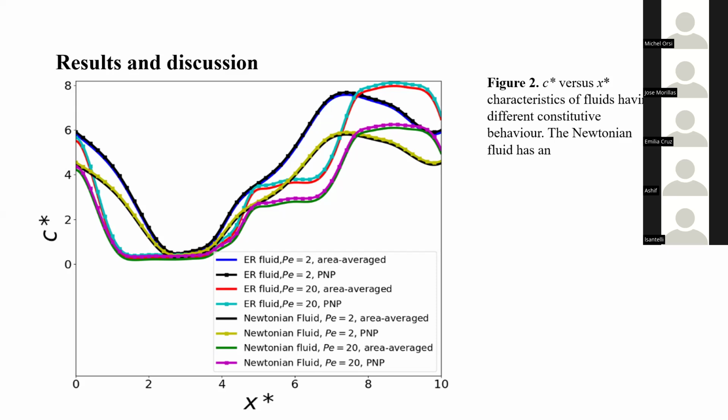Figure 2 reveals that the region around the deep to shallow junction acts as a species depletion zone, while that around the shallow to deep junction acts as the enrichment zone. In ER fluids, the velocity profile has a plug flow region, where the velocity is constant across the cross section. The region outside the plug flow is very narrow in case of ER fluids, leading to very high shear stresses.